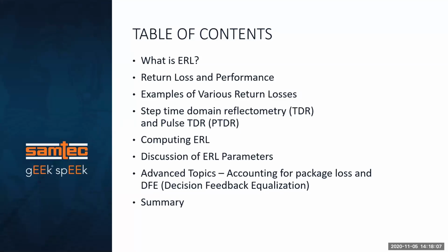What are we going to talk about? We're going to talk about a little bit of what is ERL, some return loss and performance issues. The first example is a little bit about TDR, pulse TDR, how we compute ERL, and a discussion of the parameters and how you use them in the COM tool. Advanced topics will be package loss and DFE augmentations. Then we'll finish it up with a summary.